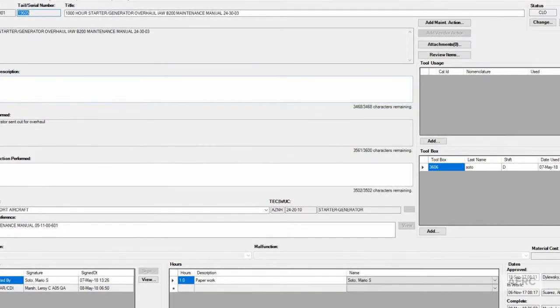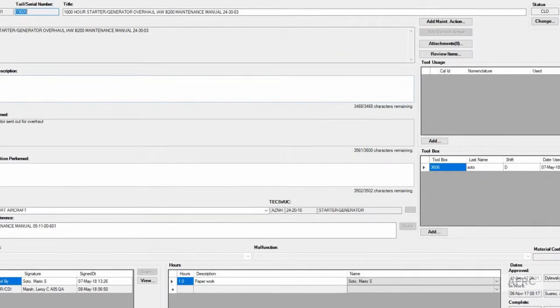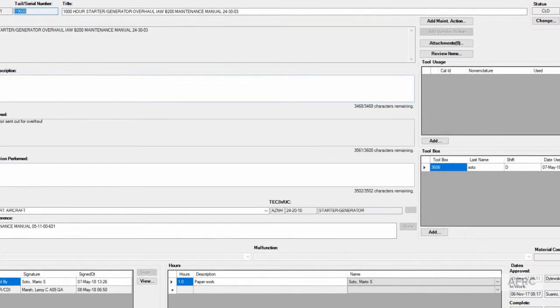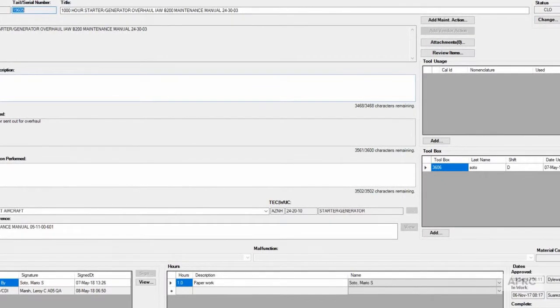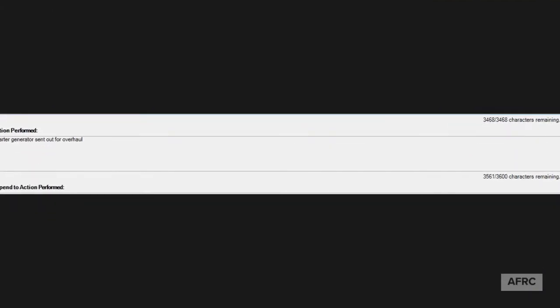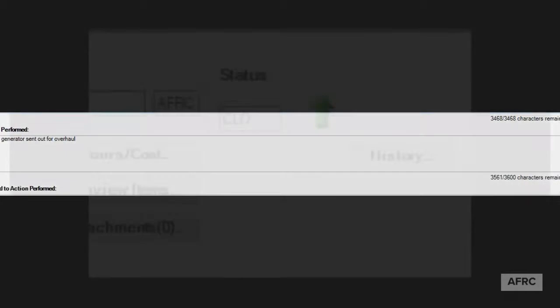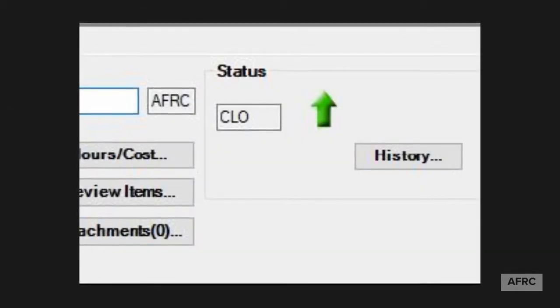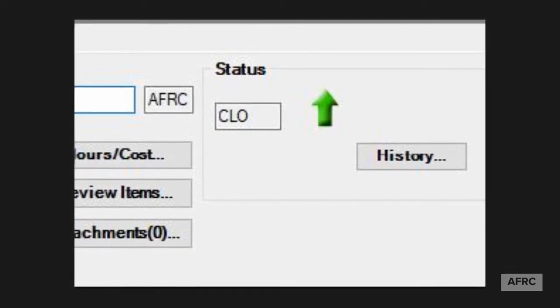AFOP 7900.3-026, that's aircraft documentation. Paragraph 6.12 outlines the procedures for changing a work request to historical. The first thing you want to look at is the corrective action and make sure that whatever was written was appropriate for the discrepancy and that it was complete. You want to look at the work request and make sure that it's being properly identified as being up or down.